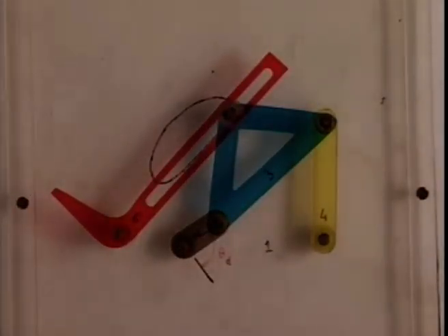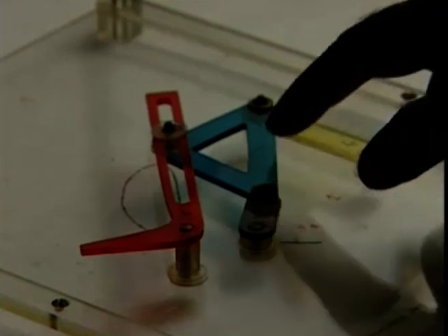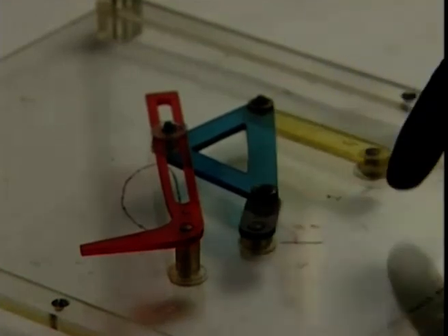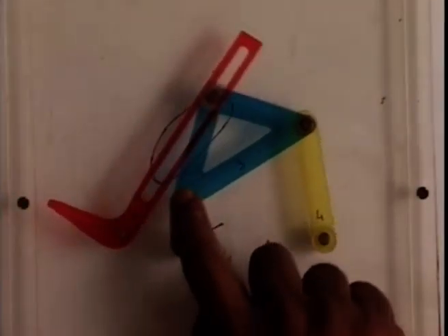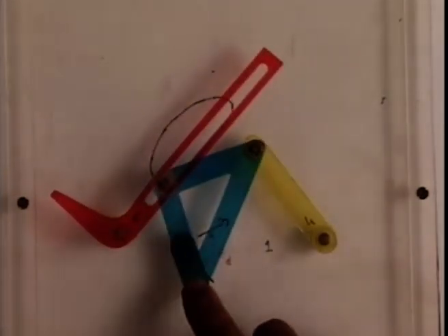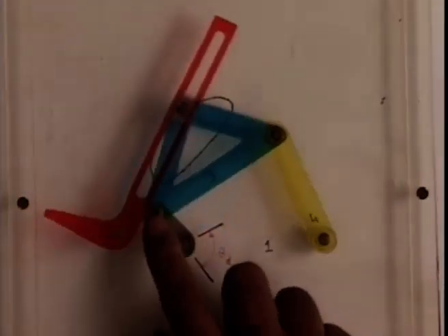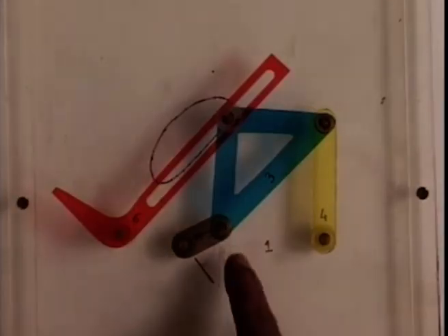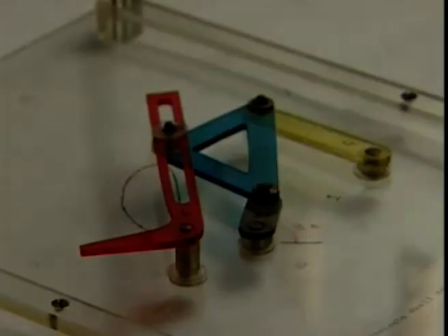As an example of a path generation problem, let us look at the model of this 6-link mechanism, which can be used as a dwell mechanism. In this mechanism, we have a 4R linkage consisting of link number 2, link number 3 and link number 4, where 1 is the fixed link. So this is a 4R crank rocker linkage. Link 2 revolves as a crank. The thing to note is that this particular coupler point, we want to generate this particular prescribed path.